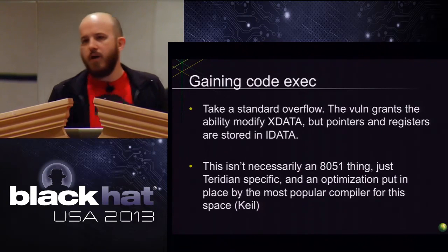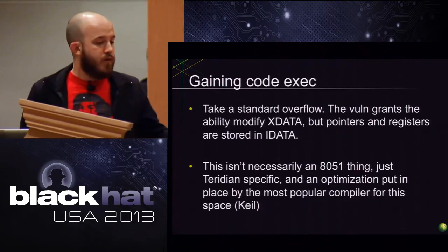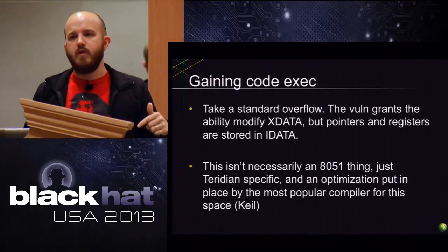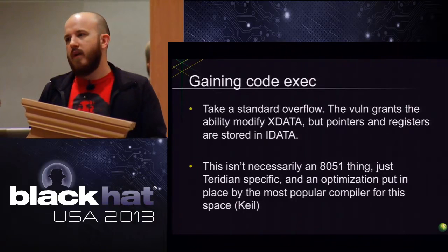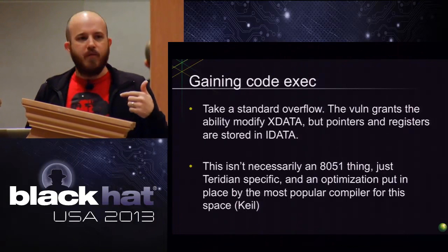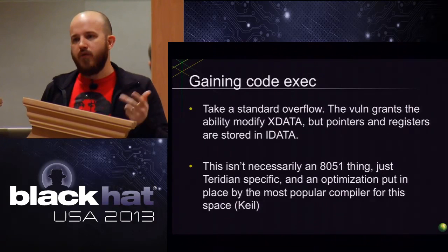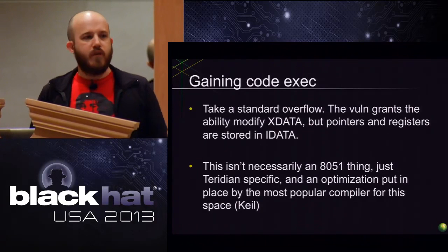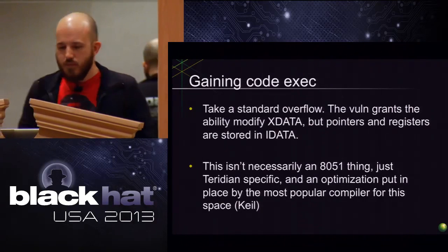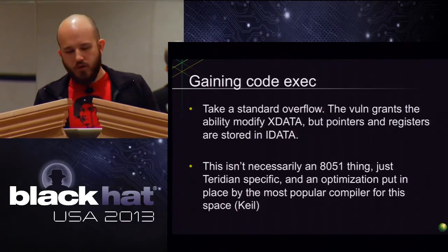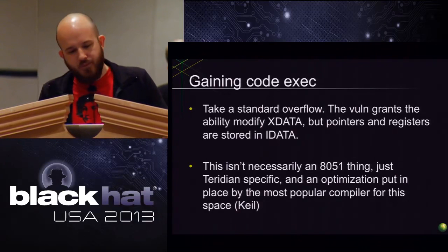So there are other, I think Travis's talk that we plugged earlier, he speaks of another 8051 implementation where this is doable because the stack is in a location that is bigger in comparison. And so the compilers for that one don't do this sort of trick where it sticks the stack over here and sticks the data over here. So in those cases, just standard buffer overflows would work just fine, but they won't in ours, unfortunately.